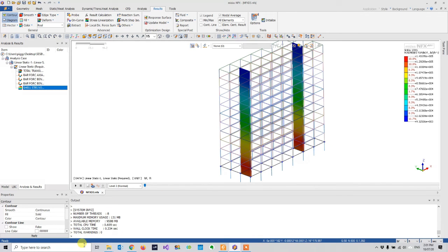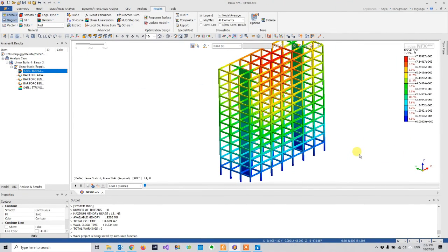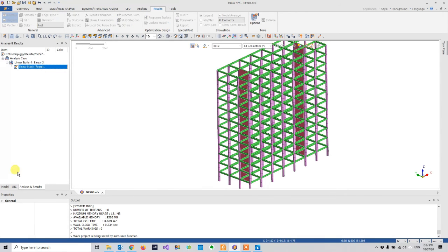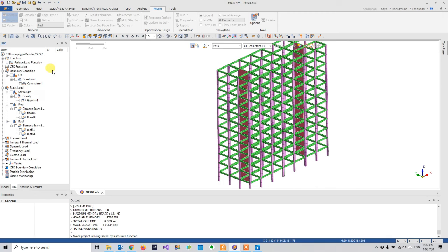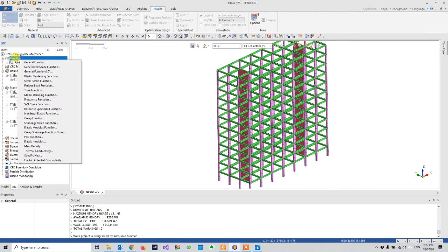So we can proceed to the next analysis, which is the seismic load analysis. Okay, let's start with some preparation of the response spectrum value that we need to excite for the vibration analysis. First of all, let's prepare some values in terms of the damping.